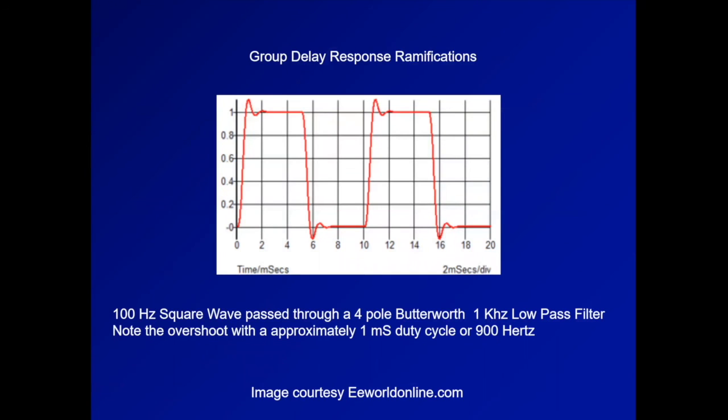You notice the overshoot looks like a sine wave. Well, in essence, it is a sine wave. That's the 9th harmonic that's not lining up in time with the other harmonics. And that actually is a telltale where the 3 dB point of the filter is being reached, where the phase rotation is such that it's so out of phase at this point that when it returns to the source, it's piling up because it's not lining up. It's popping out on its own, and that's what's happening here.